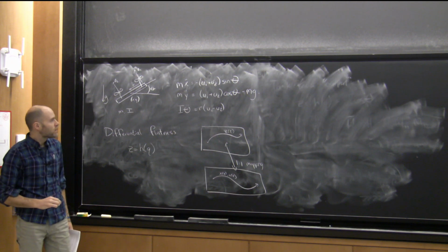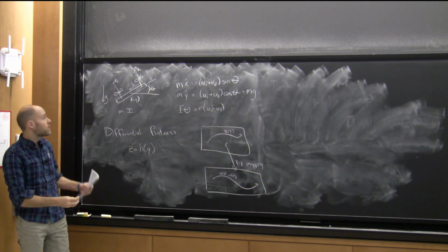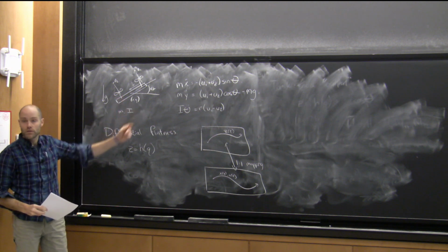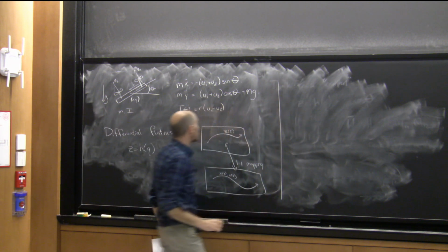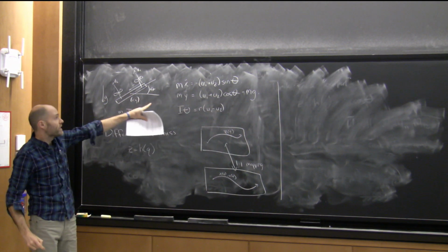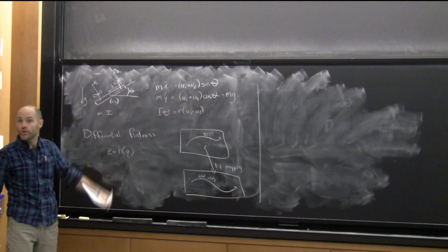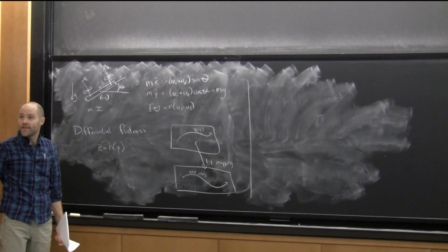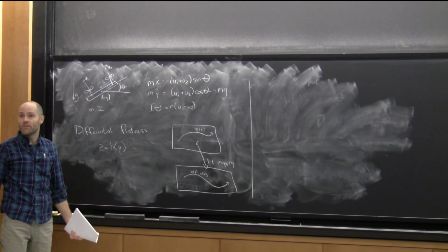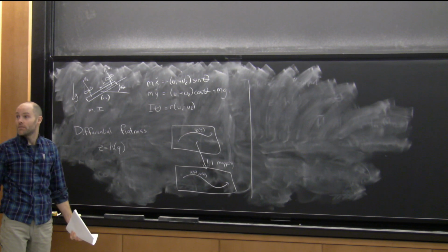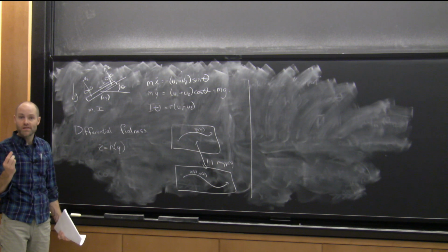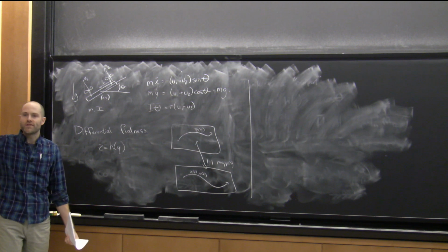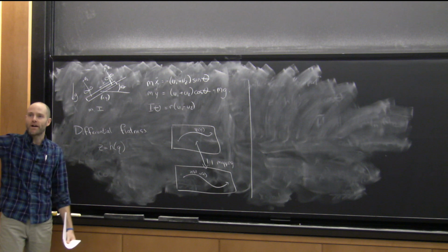Let me give you an example here on the planar quadrotor. It turns out, if you tell me what x and y are doing over time, then that's enough for me to tell you exactly what u had to be and exactly what theta had to be. You've got two actuators, you get to control two things. Let's just pick a trajectory of the center of mass over time. We're going to make it fly around the room.